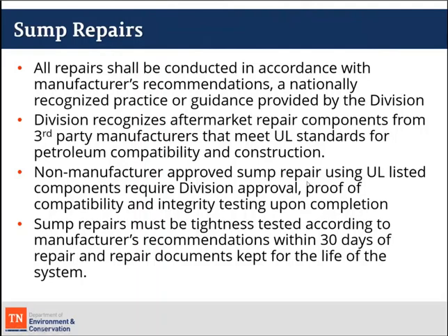So if the sump manufacturer says you can't repair our sump, but you have UL listed components, you can come to us and ask for approval of that sump repair. You're going to have to show proof of compatibility and also proof of integrity testing, some form of hydrostatic test or a test along those lines after the repair is completed.